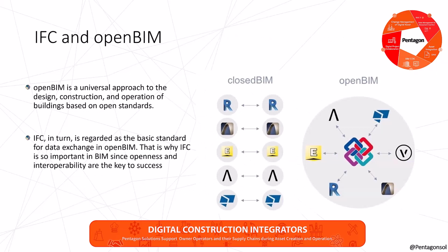Yeah, so just the relation with openBIM and IFCs, we're looking towards the future of a project, so we must consider openBIM and future-proof our project, especially at the facility management level. An openBIM approach to the design, construction, and operation of buildings is based upon open standards. So the methodology supports transparent, open cooperation of all project participants, regardless of the implemented software. So with IFC being a non-proprietary file type, it is the best solution for openBIM as it doesn't allow software applications to define the data exchange.